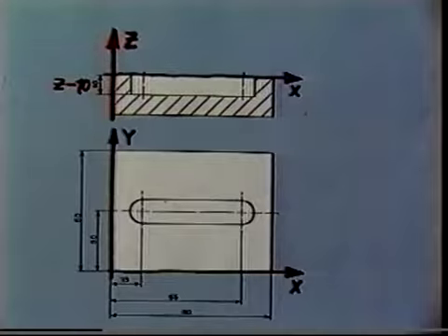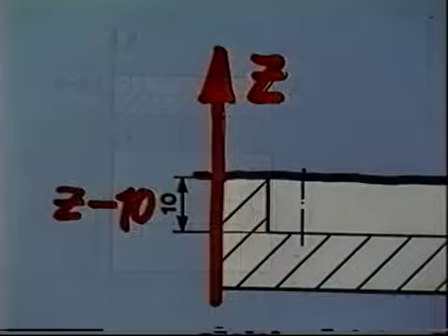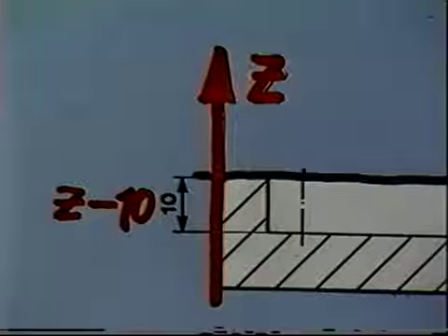Now let's see briefly how things look when we add the z-axis. Z coordinates are used to program downfeed depth. Z equals 0 is usually located on the workpiece surface, so that every downfeed movement has a negative prefix. In our example, we'll cut to the final depth, Z equals minus 10.